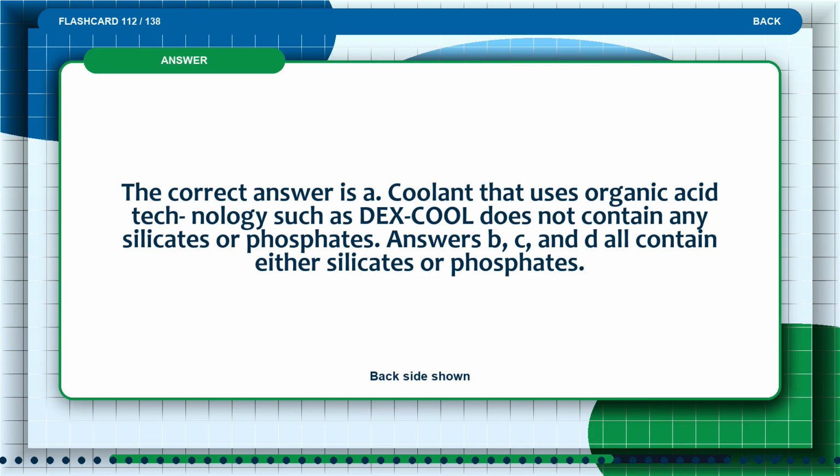The correct answer is A. Coolant that uses organic acid technology such as DEX-COOL does not contain any silicates or phosphates. Answers B, C, and D all contain either silicates or phosphates.